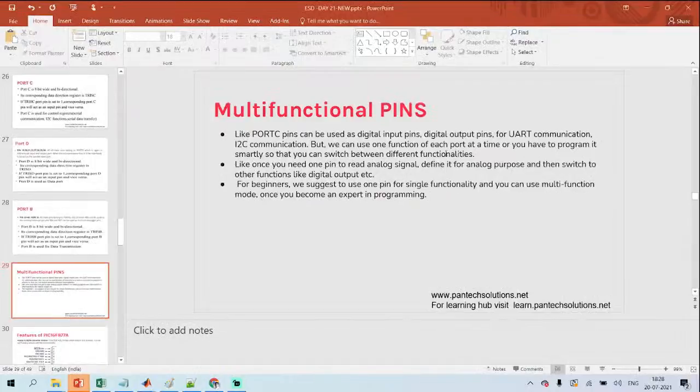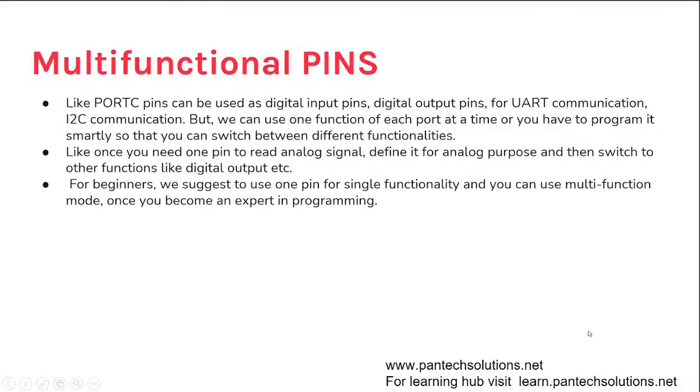Now, multifunctional pins. Initially it is better to use a pin with a single functionality, but once you are familiar and become an expert in programming, you can go for the multifunctional mode. Most of the pins are multifunctional: a pin can be used as a digital input pin or a digital output pin, or the same pin can be used as UART or I squared C. It's the same as LPC2148 and LPC4088.